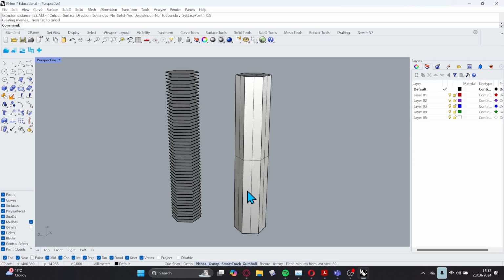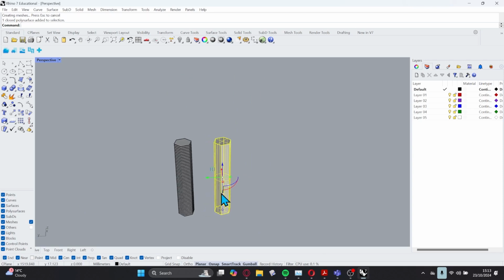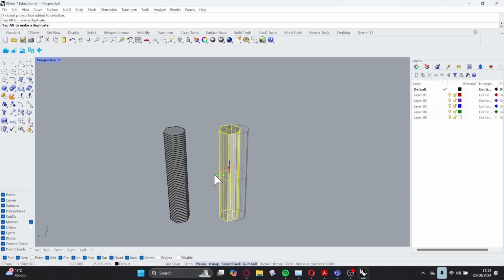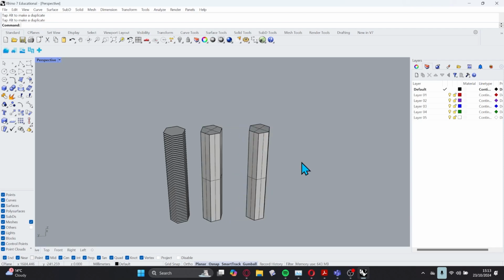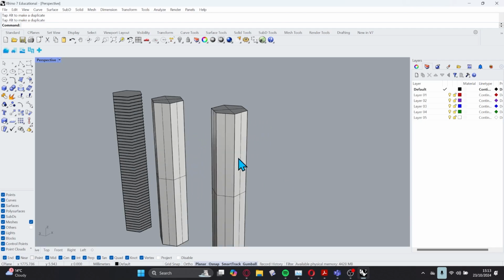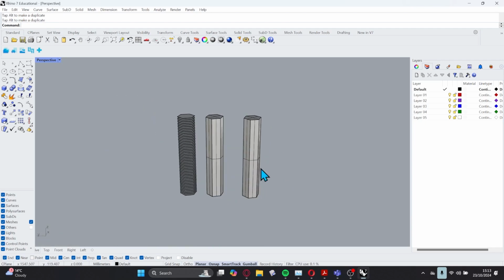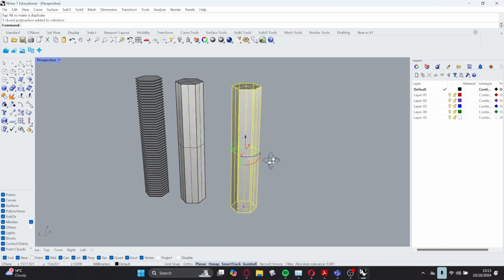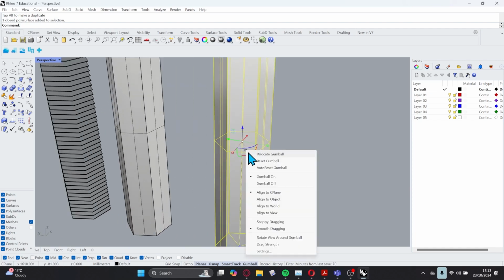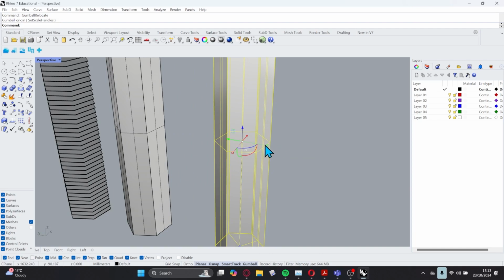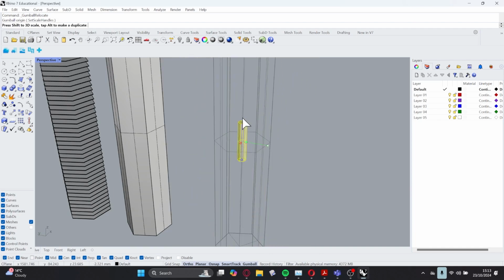Okay? Let me show you some other commands. I'm just going to very quickly show you the transform command and what we can do with those. Let's say I've got my hypothetical tower here. In order to copy it across, I'm just going to start dragging across and hit Alt 1 time. Boom. And then it's like that. To scale it uniformly, what I would usually use, as I'm scaling, is to hold Shift, and it will scale uniformly.